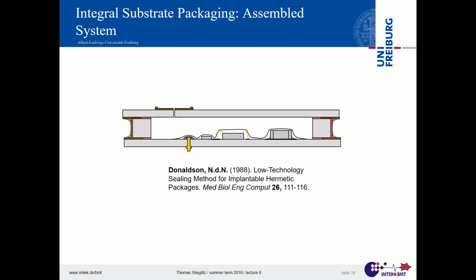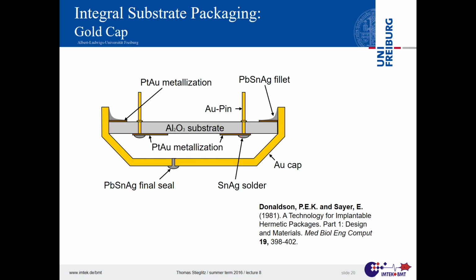If everything is assembled, we still have the hole here. We have the feed-throughs in the base plate. We have the hole, we can heat it up so all water vapor goes away, and then we can fill some helium in there for the leakage testing, and we can solder that shut. Check, done here. Similar thing, same group, can also be done if you take a metal cap instead of a ceramic cap. So you have a metal cap and your printed circuit board, and you bring it together and solder it.